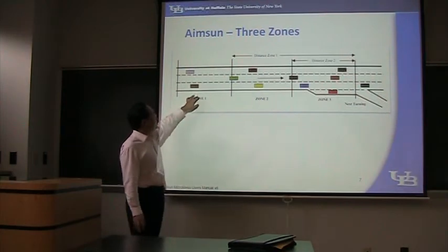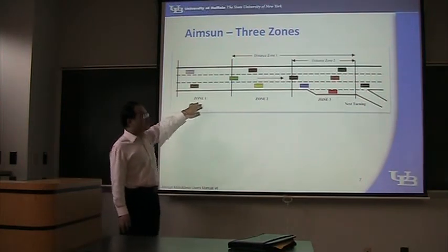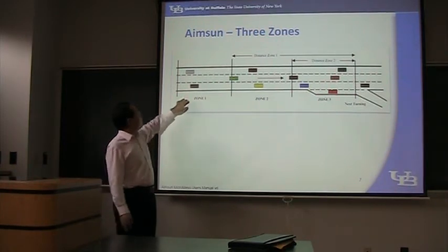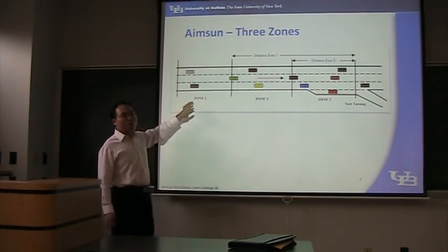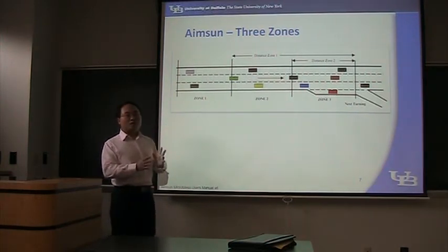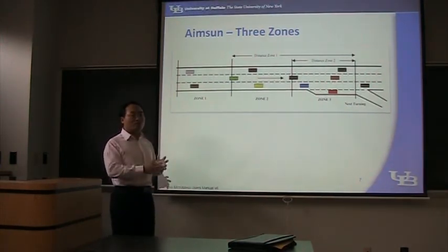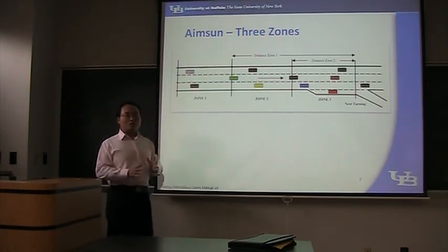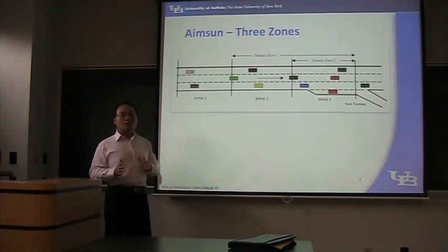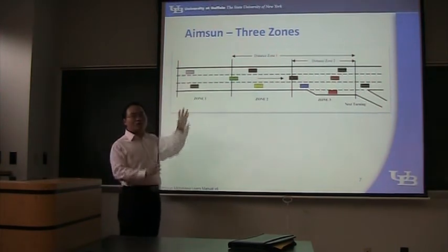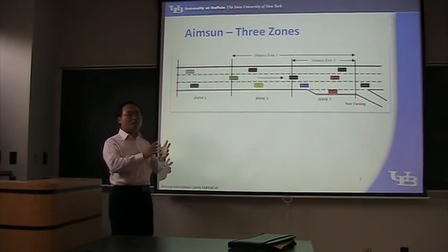The first zone is the furthest from the node or the junction. In this zone, MSUM defines that vehicles only change lanes because they want to reach better traffic conditions. So in this zone, discretionary lane changing is the most important one. Understand?